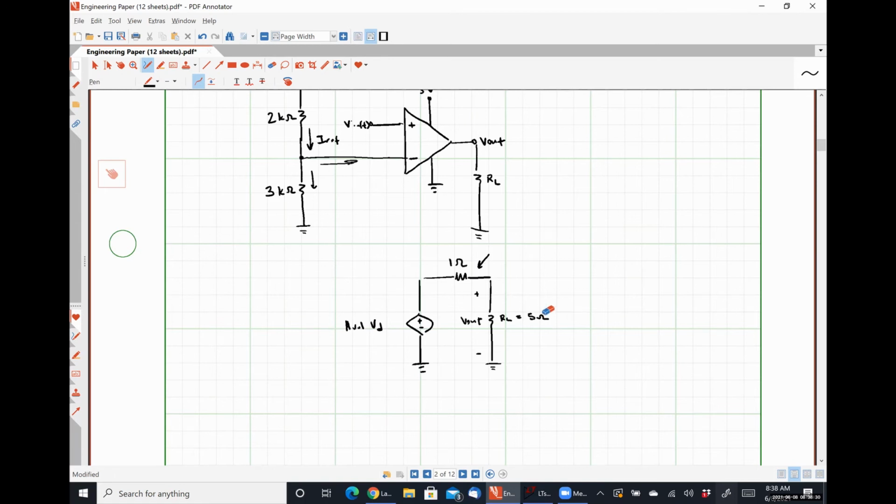If we instead made this guy a 5 kilo ohm resistor, we're going to see practically all of that expected output voltage, right? So we could additionally use a mega ohm resistor or something like that if we wanted to, but that would kind of be overkill, and it might also have problems if we were wanting to use the current that's being output by the op amp to do anything. Putting a 5 mega ohm resistor in there would lower that output current to a very, very small amount.